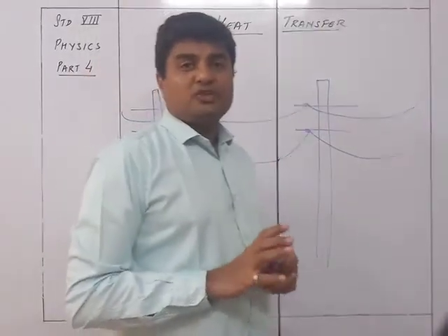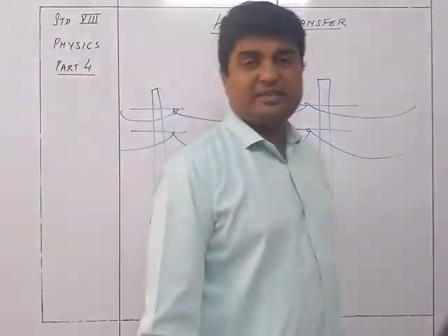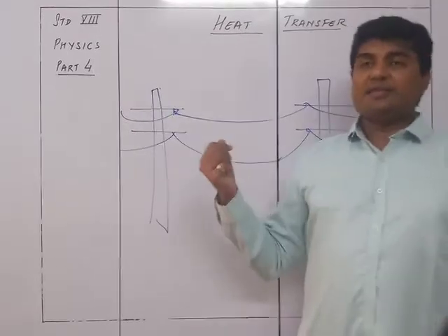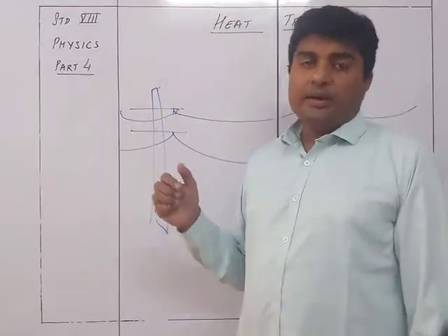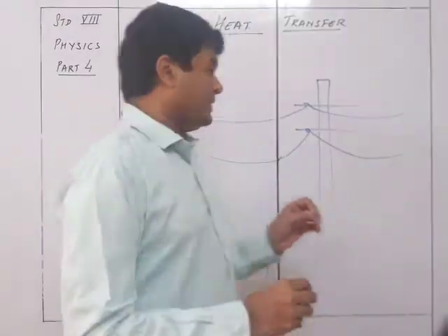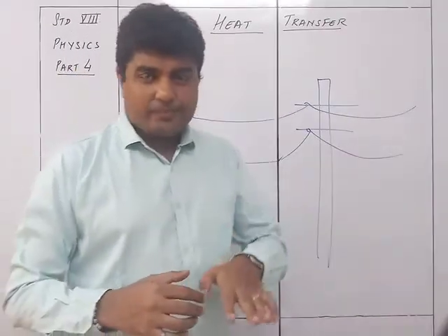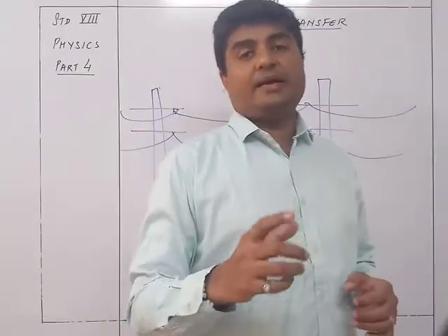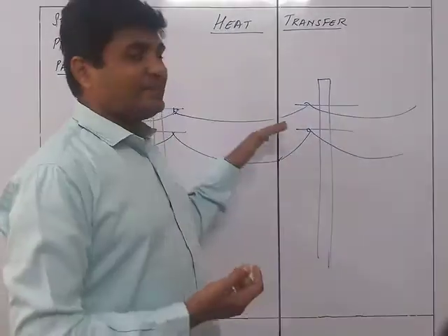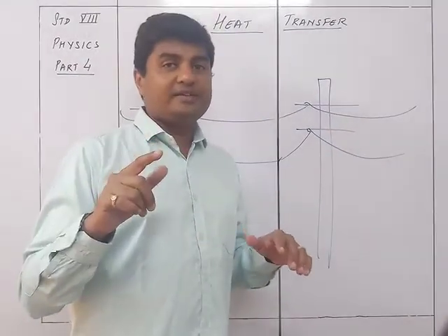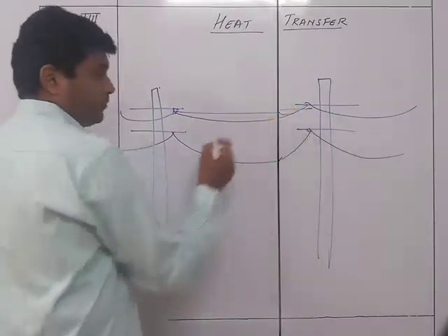Now it is always done this way: when the laying of the cable is done in the summer season, they are going to make it slightly sagging. Okay? In the summer season, if they are placing the wire from one pole to another pole, they are going to make it slightly sagging. Why is it so? Because they consider that in summer the wire has expanded, so if you keep it sagging, automatically in the winter season when the wire contracts, at that time it will almost become straight.